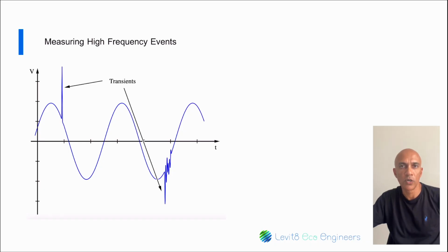For instance, 2 times nominal system voltage, which is 2 times 230 volts, which is 460 volts. It is also helpful that if you are testing for failure of specific equipment, that you try to obtain the specifications for that equipment to see what its voltage tolerances are. Then you can set up the recording to measure for any anomalies outside of those tolerances.